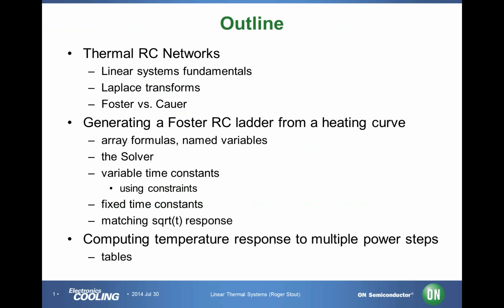The point here is to do thermal RC networks, and thermal RC networks are all predicated on having linear thermal systems, so I want to share a couple of fundamental points behind that. And then once we get into Excel, I'm going to show you how I can generate a Foster RC ladder network from a heating curve.